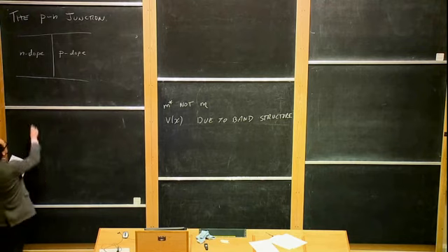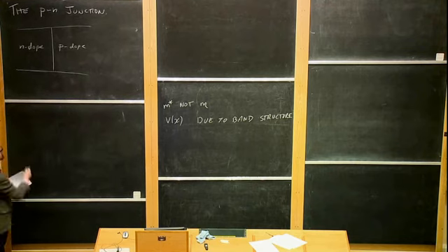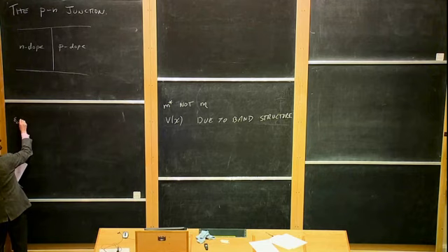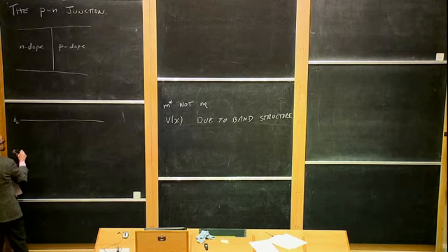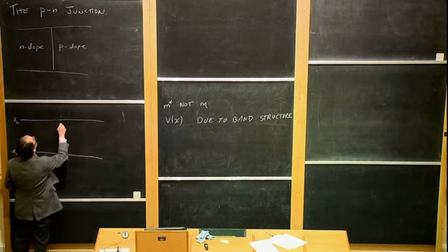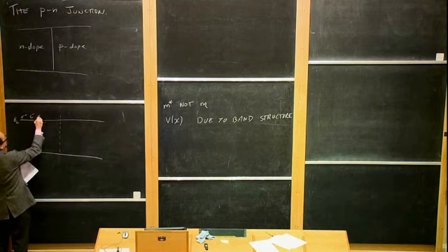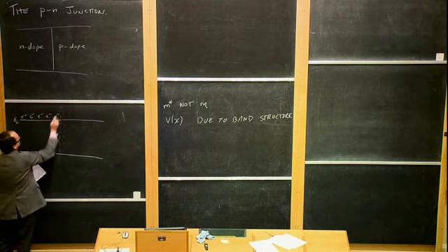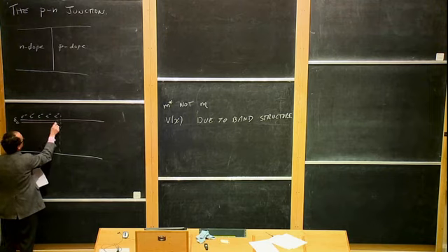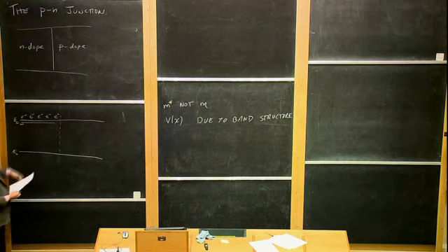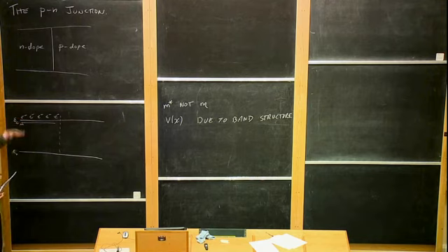And so let's draw a picture of where the conduction band and the valence band are. The conduction band energy might be up here. The valence band energy, E valence, might be down here. And here's our division in the middle. Now, over on this side, we're n-doped. So that means we have a bunch of electrons up in the conduction band here. And the chemical potential, mu, is way up here near the conduction band because we've doped it with electrons.